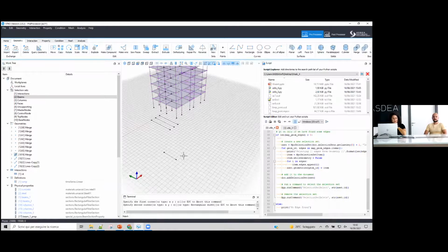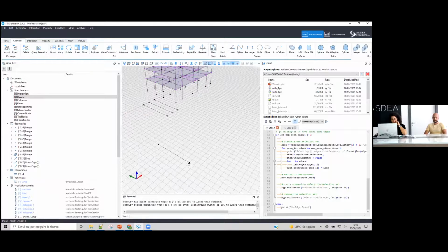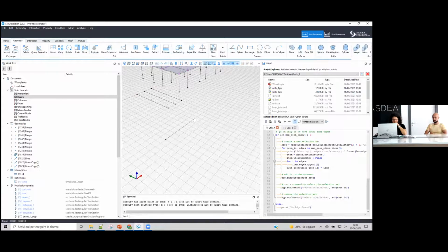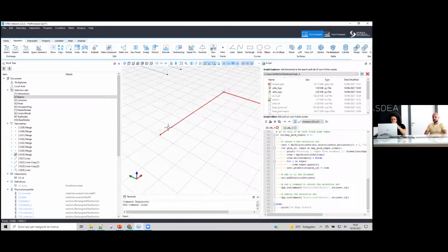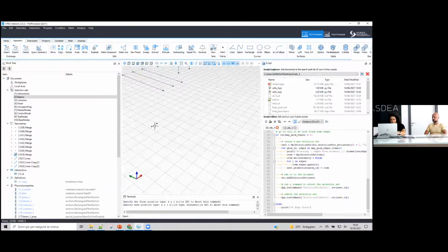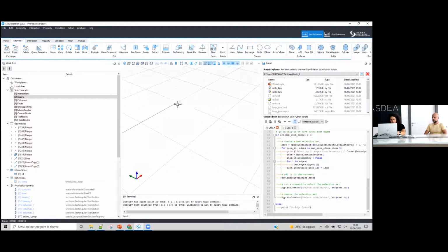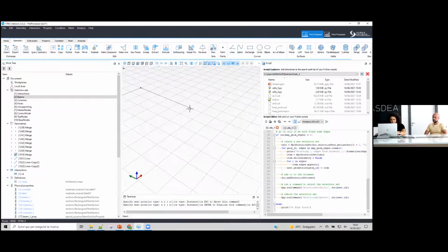You will still have overlapping geometries. Actually, when you have perfectly overlapping geometries, you can try to use the merge command, and if they are exactly overlapping, you will end up having only one of them. So you will actually remove the overlapping geometries. But keep in mind that if you have a lot of them, it will result in a complex Boolean operation. So I do not recommend doing very complex Boolean operations, because if you do them repeatedly, it will mess up your model.